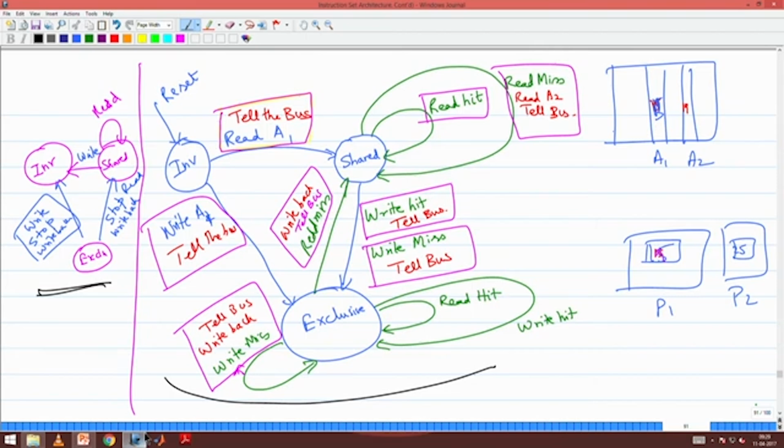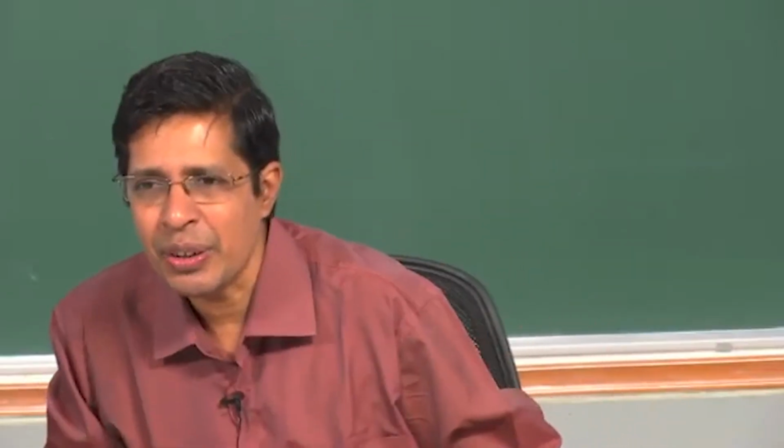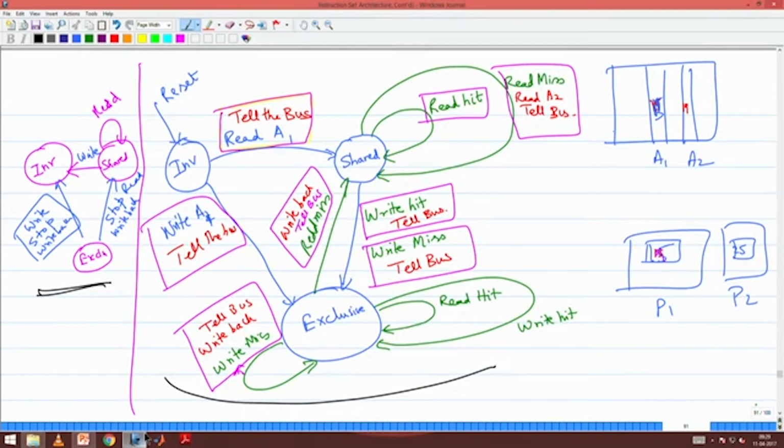So suppose you have coded this state machine in a hardware description language like HDL, you did that, right. So suppose we have coded this machine, we need to see whether it is working correctly or not. This is basically called functional verification. What we do, we give test cases to verify if it is working correctly. So what it means to verify a state machine? First thing is, we have to verify every edge. Then we may have to verify every path, from invalid shared to exclusive, invalid exclusive shared, invalid shared, shared exclusive, exclusive invalid. So different paths I can take.